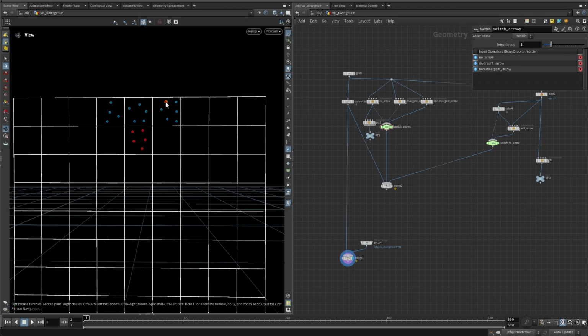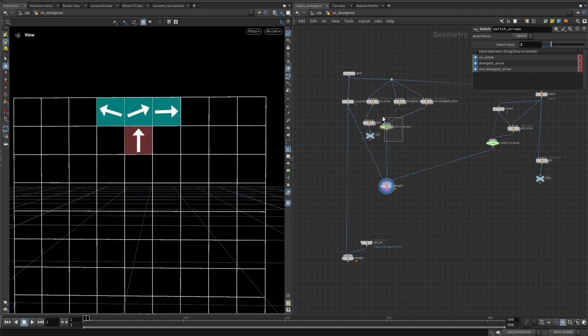We take that information and we just put it as it is in the particles. That will result in a fluid motion, but it will be very smooth, because the difference in the particle velocity, since each of these particles probably has its own velocity, is just negated. It's basically removed and we're just adding the average that we calculated in this non-divergence calculation. So that's one way. This method is called PIC, or particle in cell, and it generally gives you a more blurry fluid.